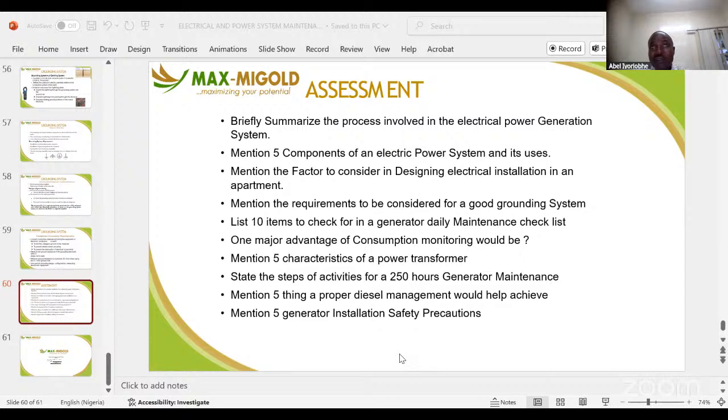So you give them like 80 or 85 kVA for your customer. That's how you determine the size of a generator. It can be applied to a higher capacity depending on the load that you have in the building. The key thing here is aggregate all the equipment power and divide by 0.8 and give allowance, but don't overgive, because if you overrate, the generator will be having issues in a short while.